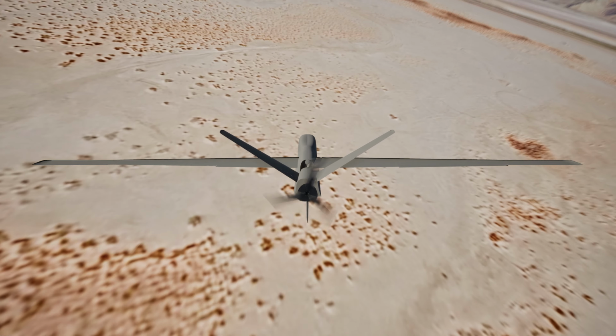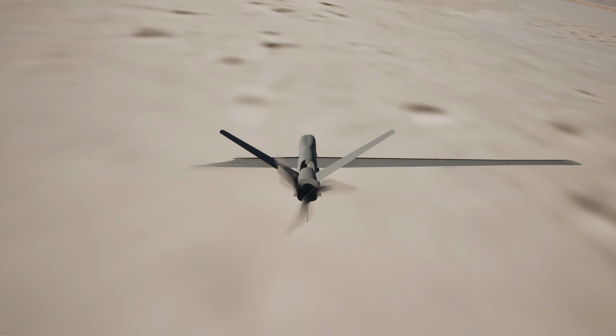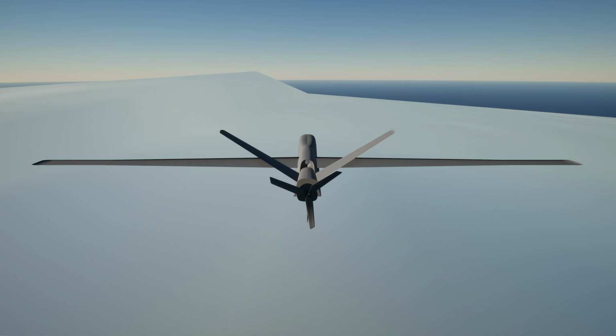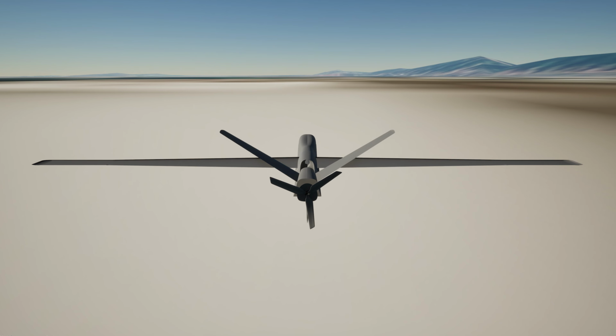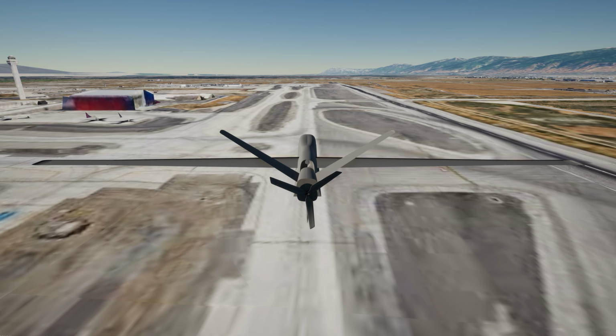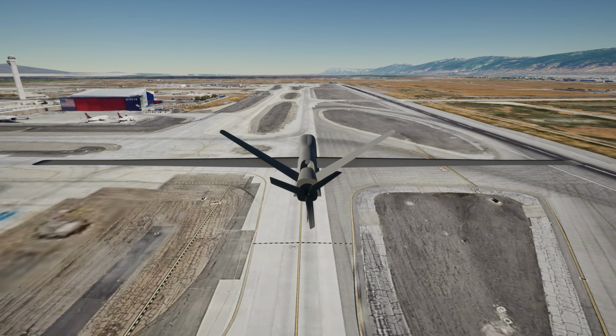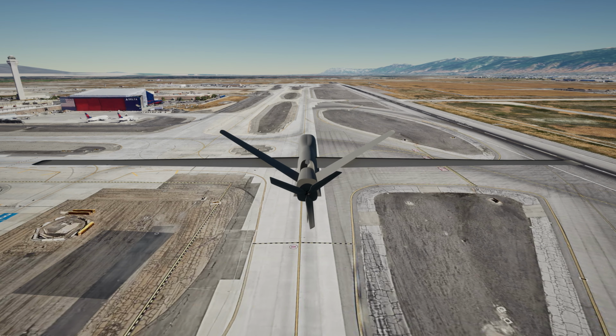So if we fly towards the ground, MAVRIK should stop. But this version of Unreal isn't sending any collision data back to MAVRIK. That's a future implementation. So you can actually fly through the terrain, through the mountains. So set your ground altitude appropriately. If at any time you get stuck or your vehicle goes through the ground, all you have to do is hit tab or escape, go back to the main menu and hit start again, and it'll load in your vehicle at the initial location. When I'm running simulations, I'll just leave Unreal Engine open and I can start and stop MAVRIK anytime I need to. So you don't need to close and reopen this Unreal Engine project every time you restart a simulation.